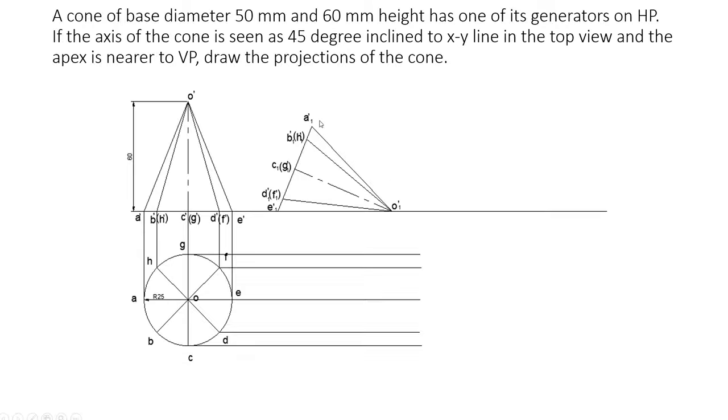Now once you get this diagram, you want to draw the projection lines. From G, F, E, D, all those points, draw parallel lines. In this case, since this line is perpendicular, H and F will be a single line. Similarly, A and E will be a single line, B and D will be a single line, and C. So you can get 5 lines here like this.